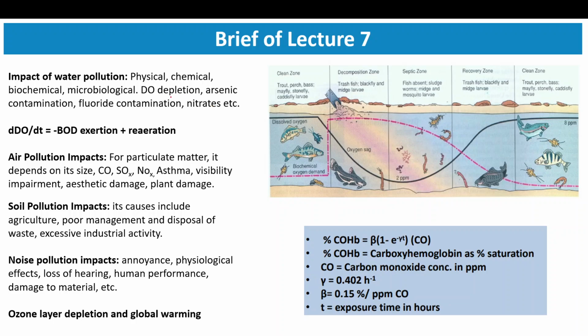So this dissolved oxygen is usually recommended to be 8 to 9 ppm in concentration. Now, if there is some water stream which has organic contaminants and it enters the water bodies, causing pollution, then the organic matter, CxHy, has the tendency to use up the oxygen to get converted to carbon dioxide and water. These are the end products. There could be some intermediate products also.